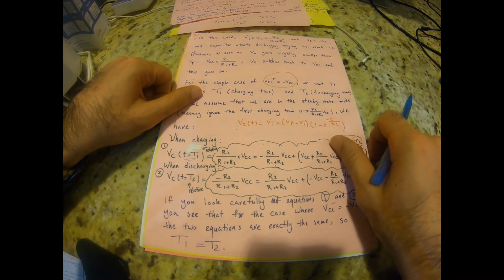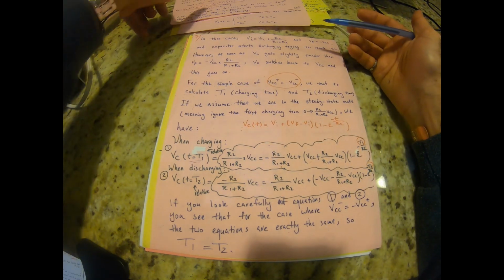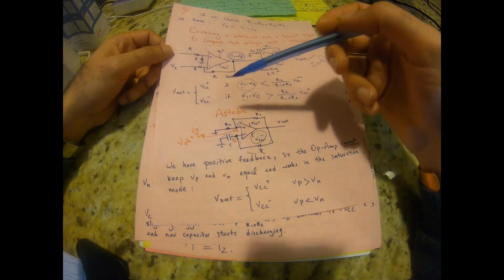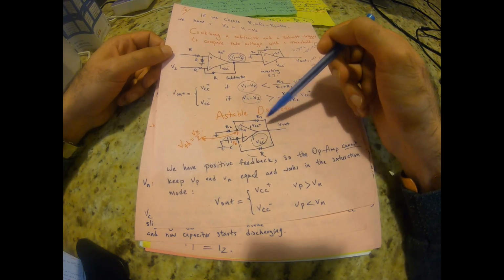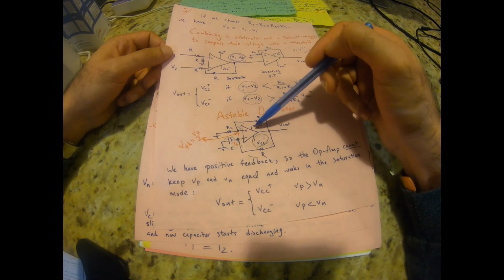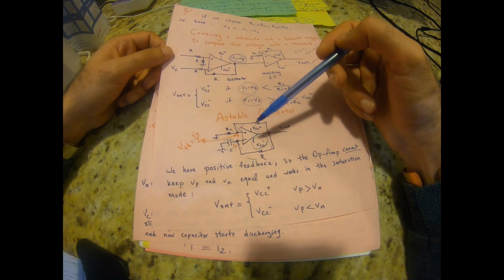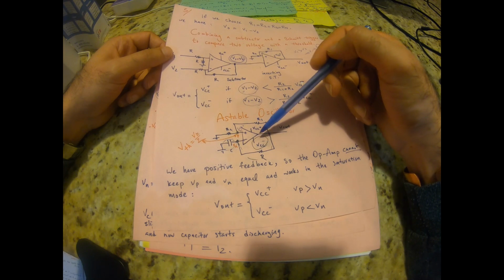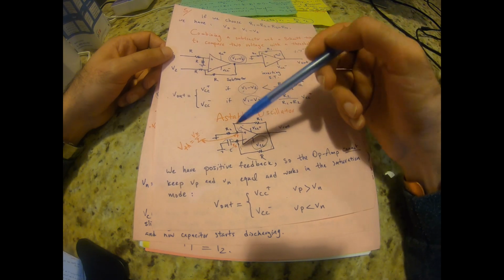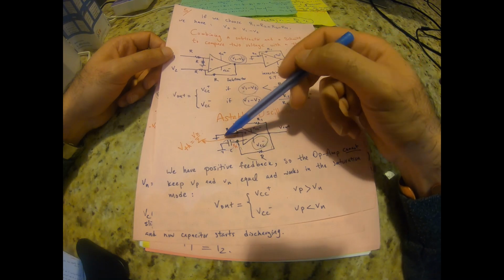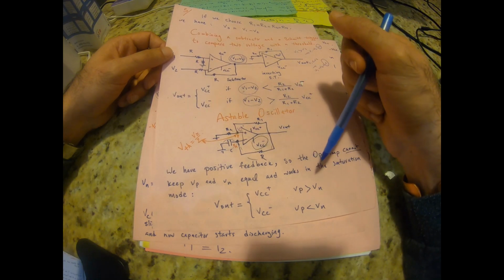Okay, so if you want to have a duty cycle of 50%, if you want to generate an output that oscillates between two symmetrical negative and positive power voltages, then this would always satisfy the equation. Doesn't matter what the values of R and C are, you end up with 50%.